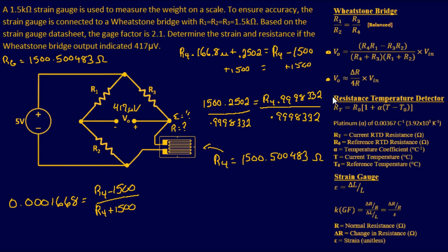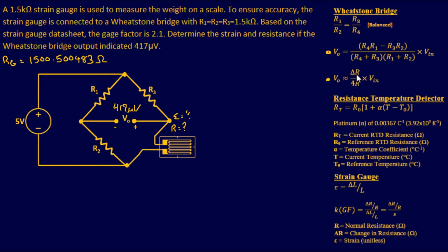So I'll tell you what, let me go ahead and clean all this up. I'll go ahead and keep this answer right here. So anytime they refer to R, they're referring to the Wheatstone bridge. What is the balance? What is each resistor supposed to actually weigh for R? So it's referring to the 1500, because if every single one of these were 1500, your output voltage would be 0. So right now, if they're referring to the difference, they're referring to the difference of your actual strain gauge, and whatever that difference is from the 1500, that's the value right here.